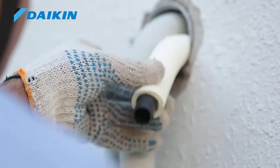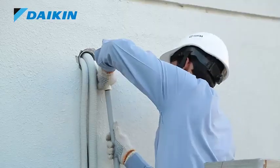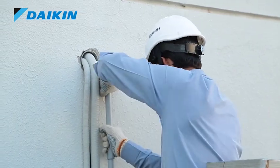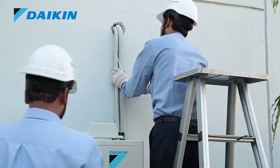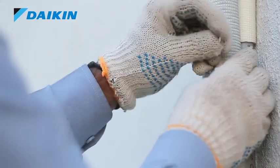Attach the flexible drain pipe, which is supplied with the unit, with the drain pipe. For horizontal drain pipe, minimum 1:100 slope should be provided, so that condensate water is extracted and drained easily, thus positioning the drain pipe accordingly.